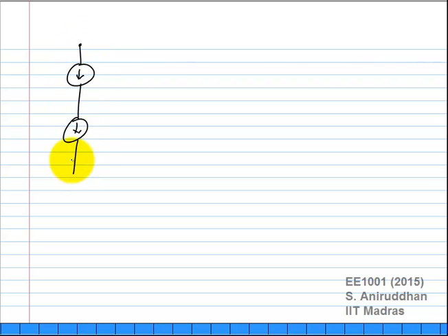What about current sources? Can I do this? I can't do this because KCL will be violated at the intermediate node. Unless I1 equals I2. And in that particular case, if I1 was equal to I2, what is the value of this?